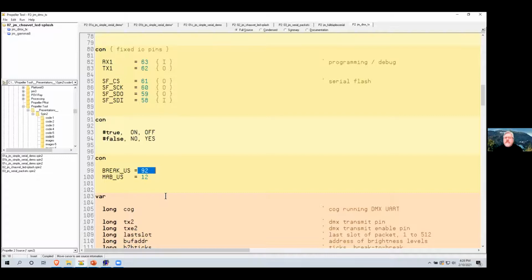So when I'm doing animation stuff like on Annie and Tibbers, I don't send 512 bytes. I'm only using about 40 channels, I think. So I have a smaller universe, which means my time from break to break can be shorter, which means I can get nicer, smoother animations.